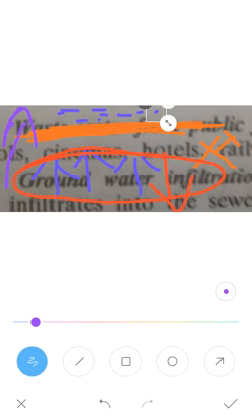The groundwater that infiltrates through the sewers depends upon the nature of the soil, the materials of the sewers, the nature and condition of the sewer joints, the depth of the sewers, and the position of the water table. So this is about the sources of the dry weather flow. Next we will see the factors affecting the dry weather flow in the next video.